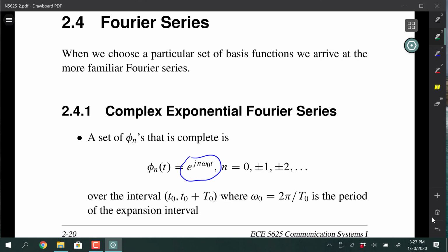So there's slight differences between the spectrum that we're talking about. The line spectrum, the spectrum of a Fourier that we get with the Fourier transform is continuous, but may have delta functions in it, and we're going to couple those together. So Fourier will be all under one umbrella, but then the power spectrum is a slightly different twist on things, but that is kind of the ultimate goal, because that's what an analyzer measures. It measures the watts per hertz of bandwidth, or if it's a discrete spectral line, then it's watts in dBm, usually right on the spectral line.